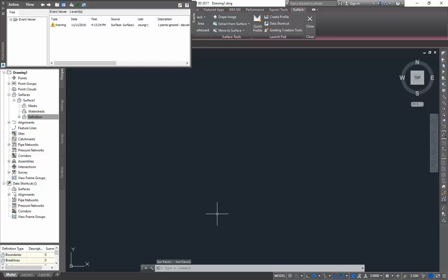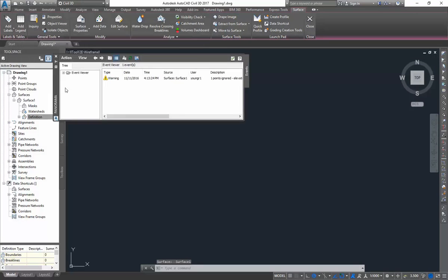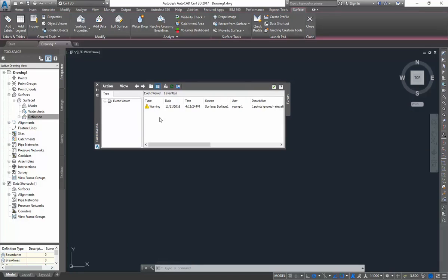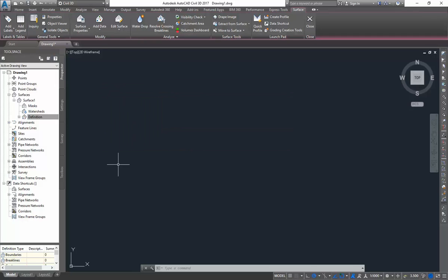Go ahead and hit OK. Now we are going to get a warning, and this is sort of intentional. Remember when we looked at the data, the very first line of it had, I think it was 5182. So that was just a descriptor of the sub-data set or the identifier with it, but that data didn't conform, right? It didn't have a northing, easting, and a Z elevation, so this warning is just telling you one point was ignored, the elevation was below a given limit, is what it says, but really it was just that it was non-conforming and it didn't have information. So we'll go ahead and close that.